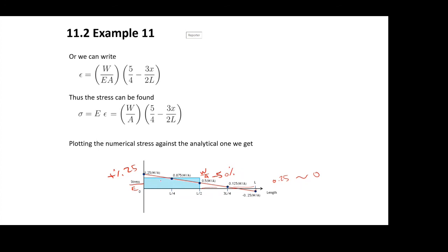Now this is happening because the finite element method is limited to the approximation you introduce into the method, right? See, the finite element method is trying to have this line matching this step function. You have x here, and this is, for example, the stress. So you have a step function, the stress is constant, and then immediately drops to 0, and you are trying to fit this step using one line. There is no way the finite element method is going to do better than what it did here. So this is why it is limited.